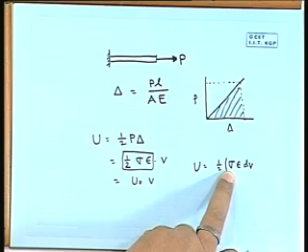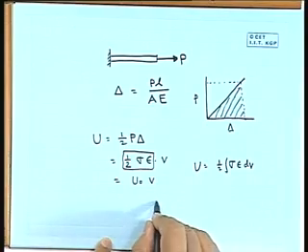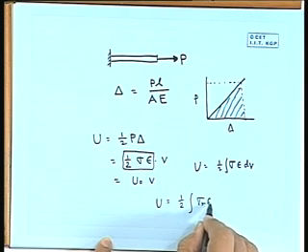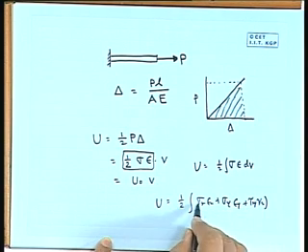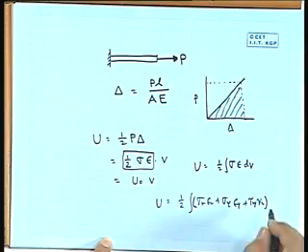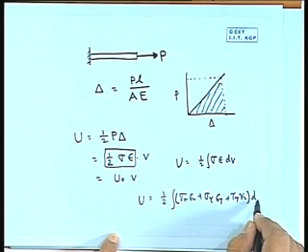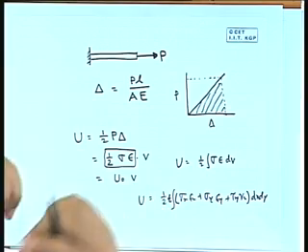So in that case we can define sigma x multiplied by epsilon x plus sigma y multiplied by epsilon y plus tau xy into gamma xy. So for a specific case we can write in this form for a biaxial system of force, say it is sigma x epsilon x, sigma y epsilon y, tau xy gamma xy, into dV. Say if we take a thin plate, we can take it is dx dy, and we can multiply it by thickness. t is the thickness of the plate.